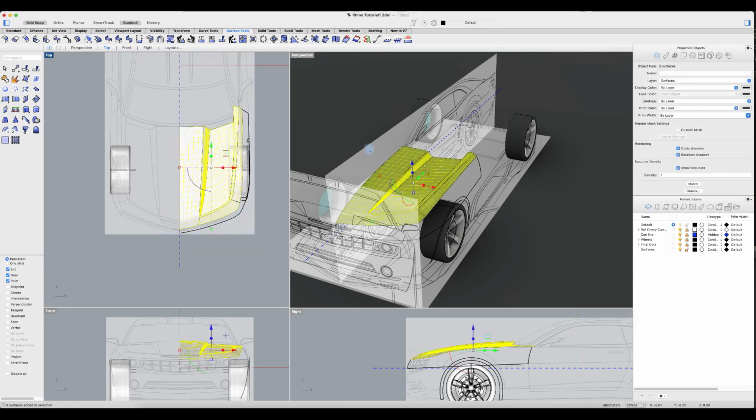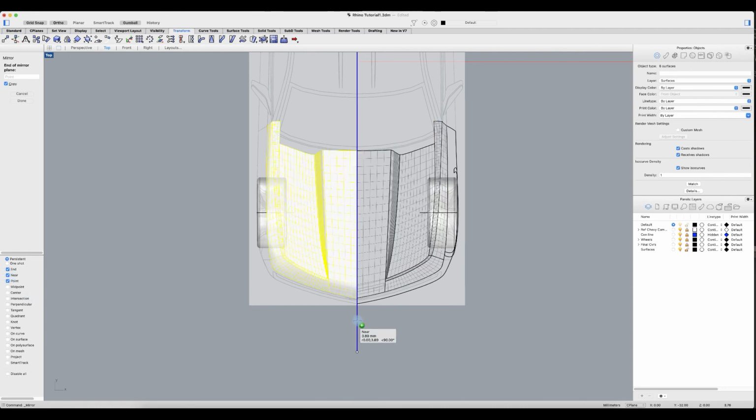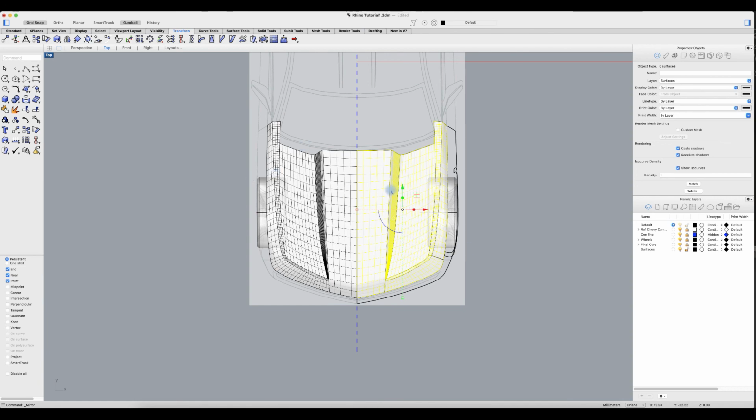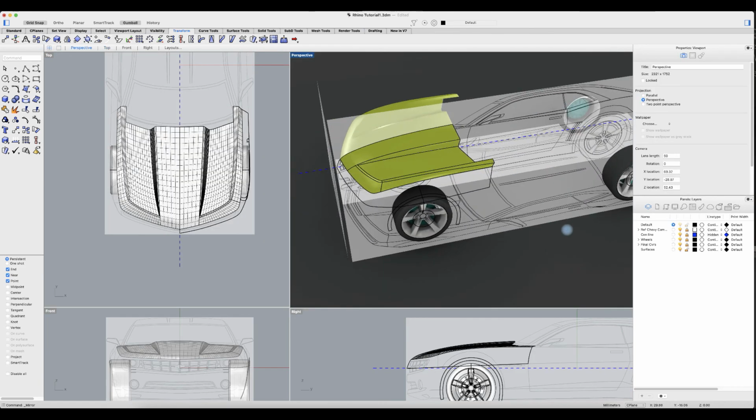And so if I select just what I did in terms of surface and I go to transform and I want to use my mirror tool, I would turn on my N which stays on, click on that, hold on my shift key, and I'm able to perfectly mirror that to the other side.